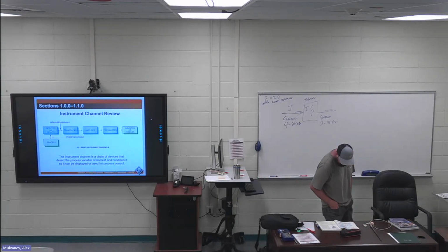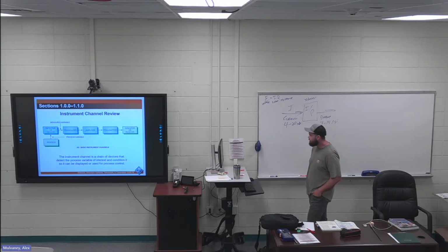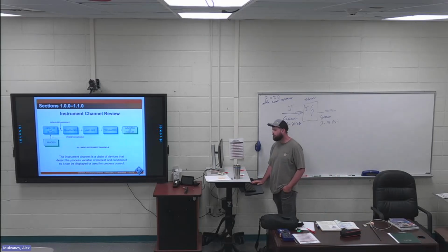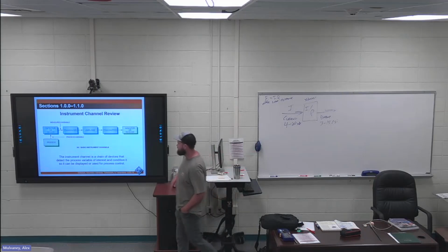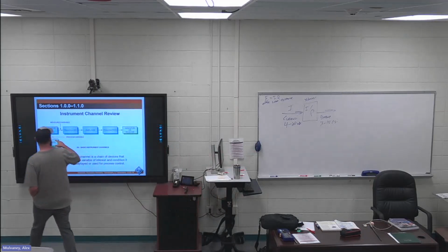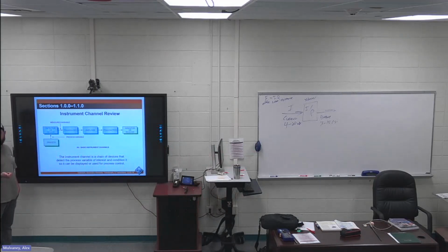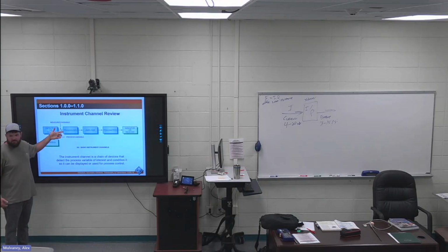All right, so pages 2 and 3. They talk about panel review. This is where you would have your detector or sensor. Remember, detector or sensor would be like your thermocouple. It's actually touching the process. What's the range? That detector can go into a transducer. Maybe it's an I to P, right? This is inputting the current and outputs a pressure.